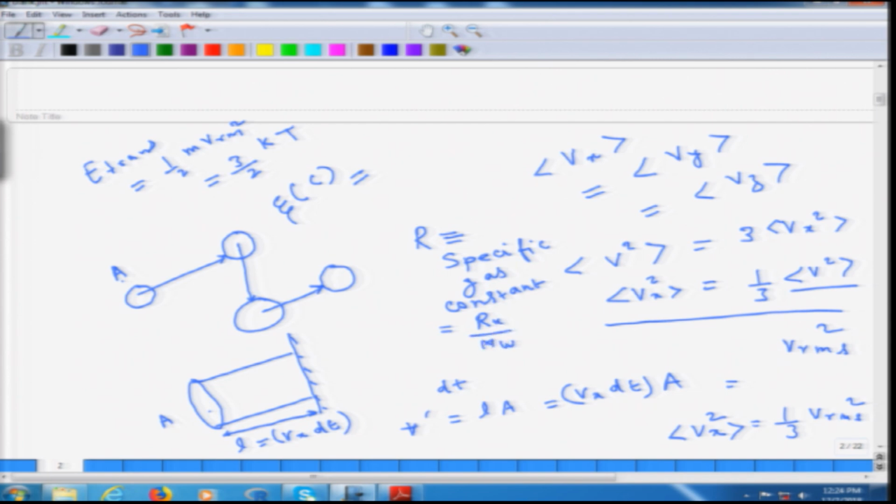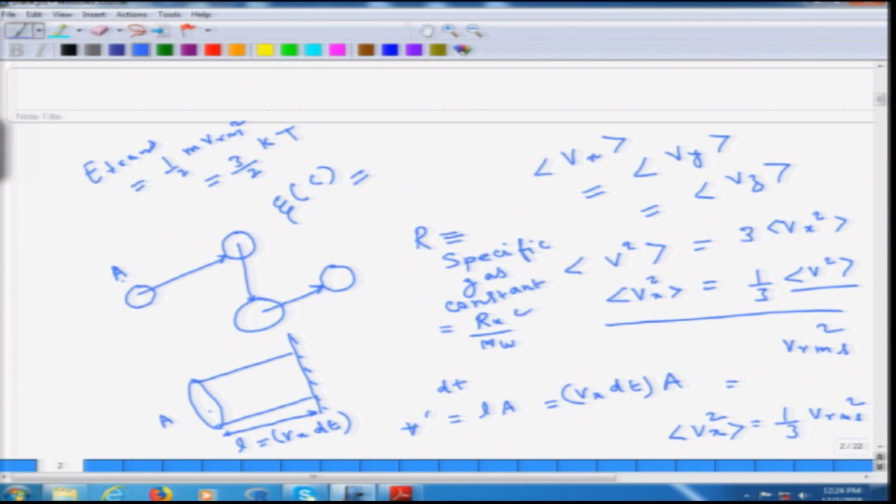For air, which is very important, because fluid dynamics, incompressible flow and compressible flow, is a generalized branch of science, but for aerospace engineering our fluid is none other than air, where our aerospace vehicles are flying. Therefore, we are more interested in the expression for air. Using 8.314 for the universal gas constant and a molecular weight of air of around 28.97, the specific gas constant comes to around 287, which we use in numerical expressions.